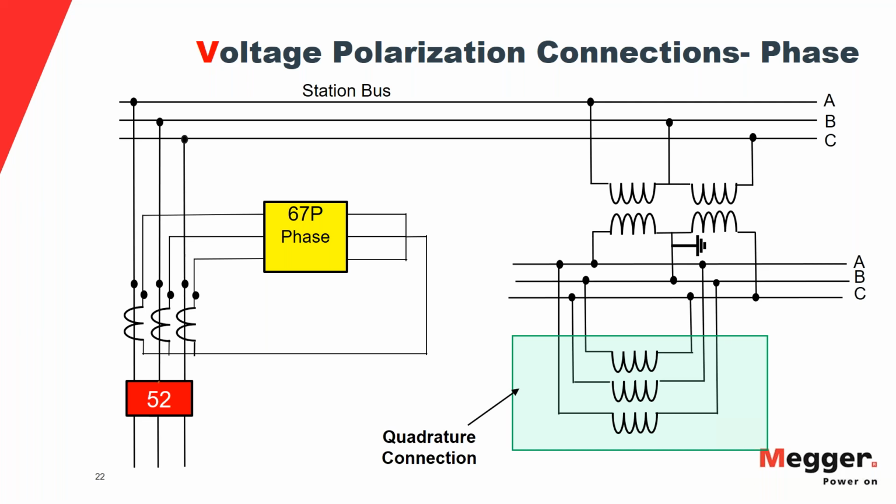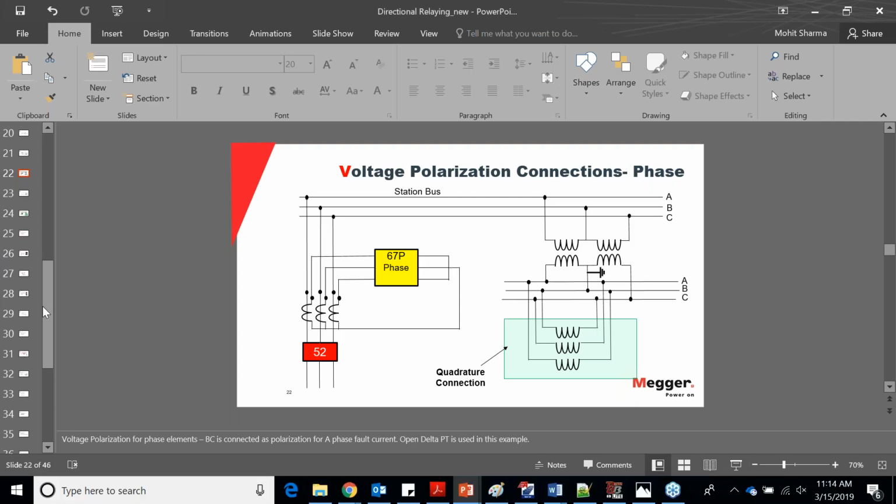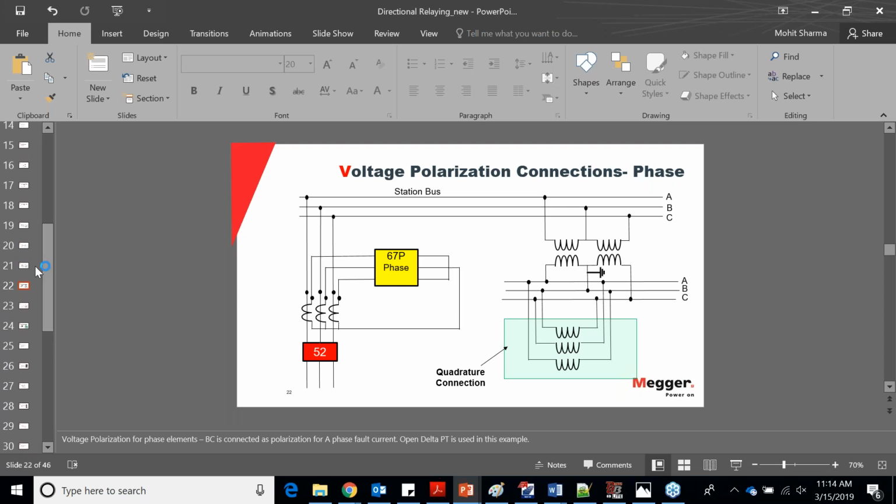Okay. Next question is for Mohit. If fault current always lags the fault voltage, please explain how the MTA could be advancing the polarizing voltage. As I explained earlier, fault current can lead the fault voltage as well. The MTA is decided on the basis of the polarizing voltage. It takes the polarizing voltage as a reference, and based on that reference quantity, you can have the MTA.